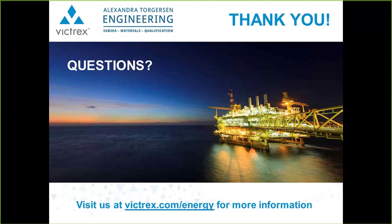So if after your aging period you take a sample out and you don't see a lot of change, but you can do a DSC on some of the material, you may see that there is some indication of degradation by looking at the DSC charts, and that again would indicate that you needed to keep your test running longer to see some kind of change in mechanical properties.